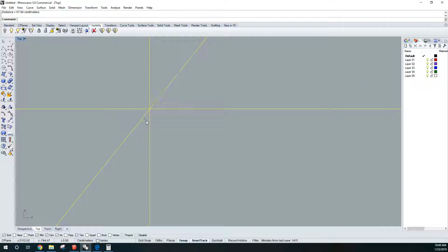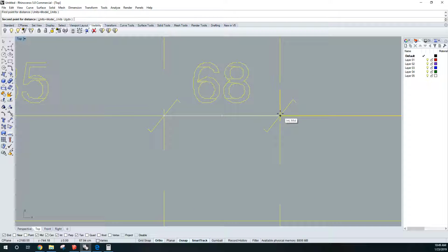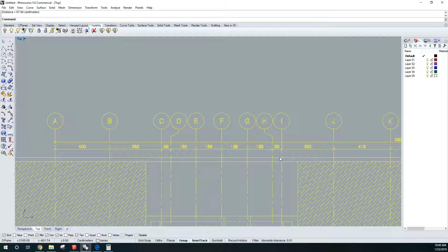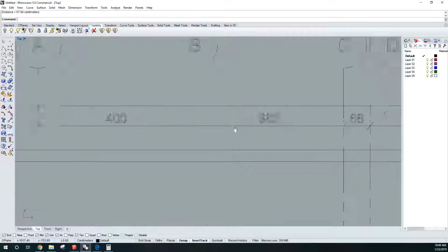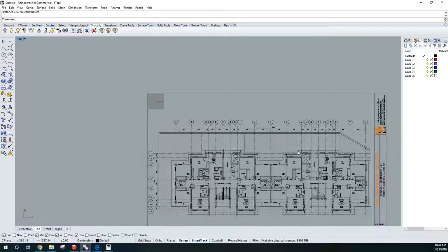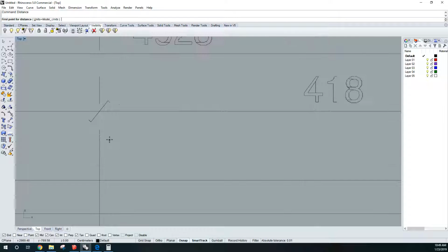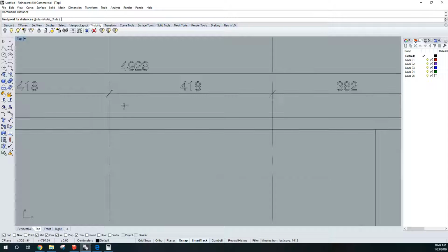I'm going to zoom in a little bit again. So at some point, the accuracy of this CAD file, 67.94 centimeters. We're going to go ahead and say that's close enough because, I mean, they should be exact, but when you take a bigger dimension string, that's where we're getting the most accuracy. I'm going to go ahead and grab it, not from that cross mark, because we could be getting a different result. I'm going to grab it from dimension string to dimension string.